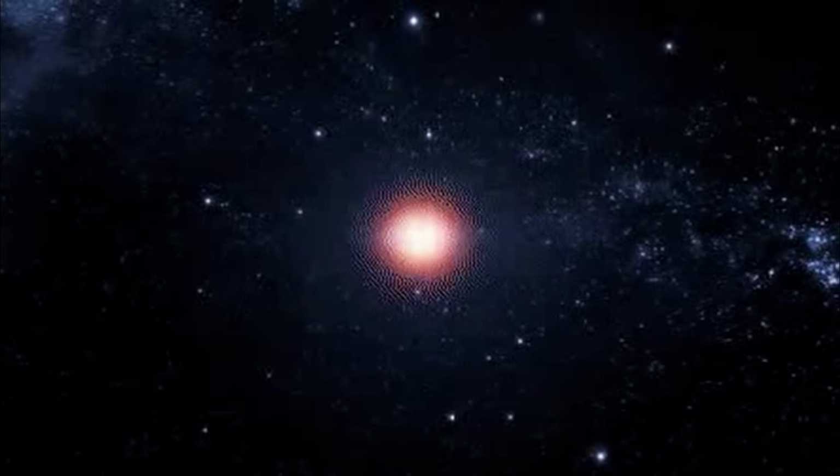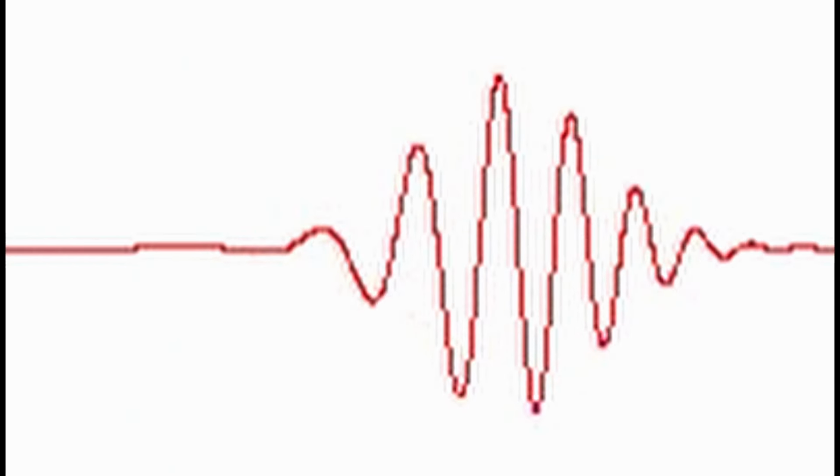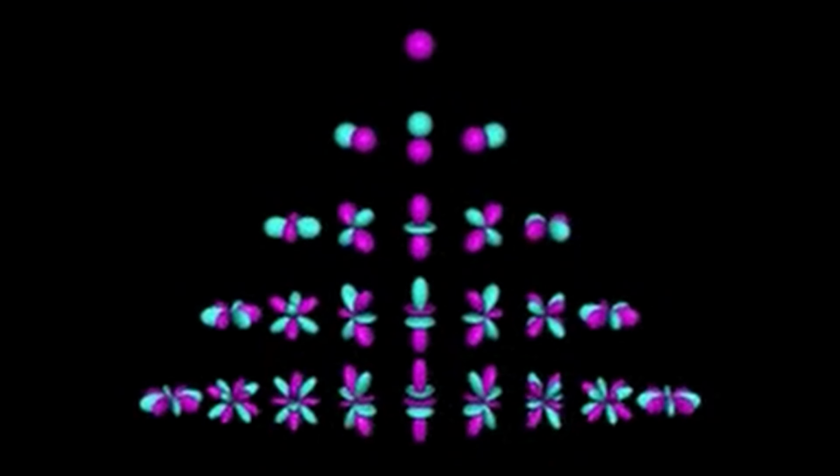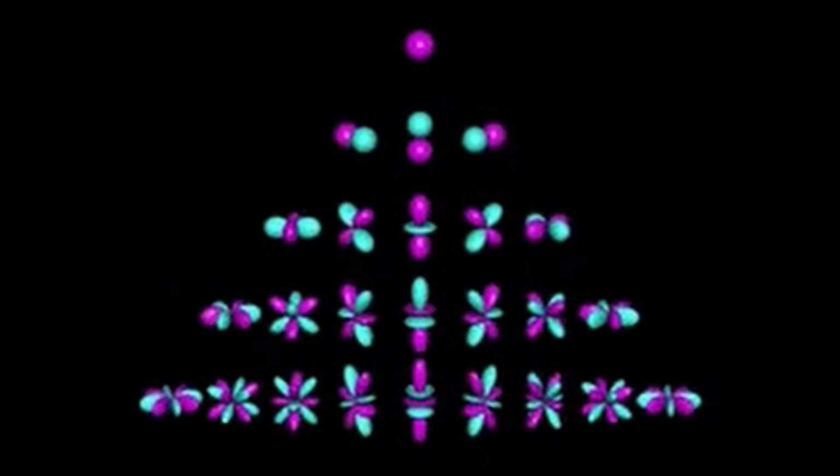It is given by R equals (Z2 minus Z1) over (Z2 plus Z1), where Z_1 and Z_2 are the impedances of the two media, which depend on their permittivities and permeabilities. Transmission coefficient T. This describes the ratio of the transmitted wave's amplitude to the incident wave's amplitude. It is given by T equals 2 Z2 over (Z2 plus Z1).